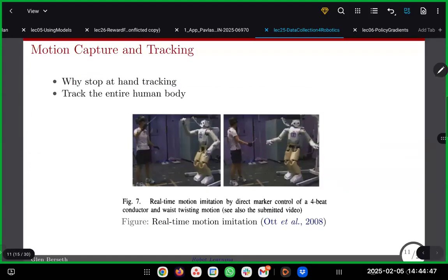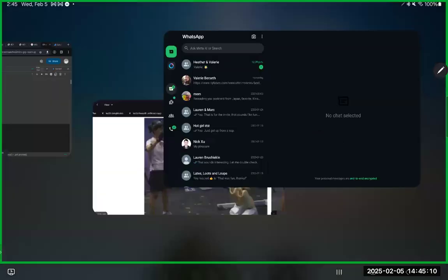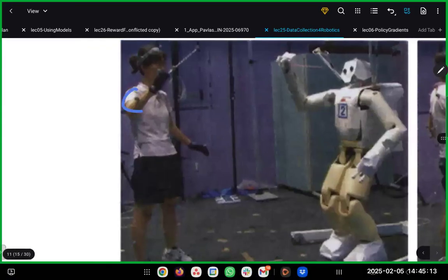Okay. So then there's beyond this, because this only works inside of a mocap system. And if anyone has ever used a mocap system before, it's only going to work inside this very special room when the human being is wearing these little reflective markers on their body, which you probably can't see too well. Let's go back to that. These little circular things are used to capture how the person is moving. And those need to be attached. And if those move at all, you need to go back and recalibrate the motion capture system, because the system will now think that the person's arm has grown, and then the dynamics and kinematics mismatch will start to grow as well.